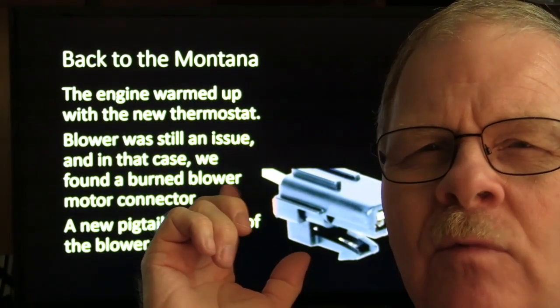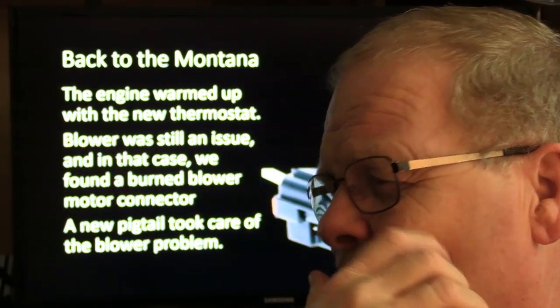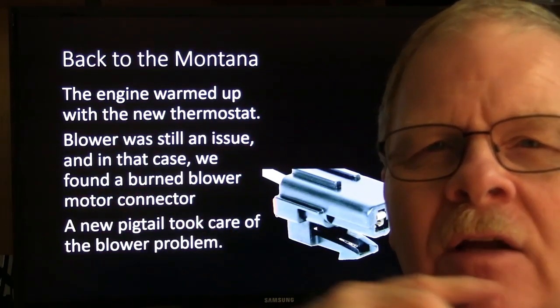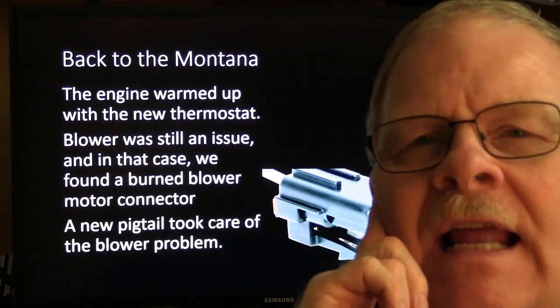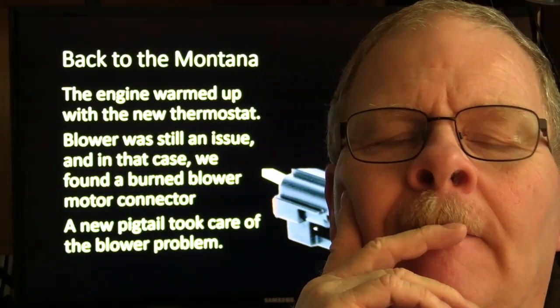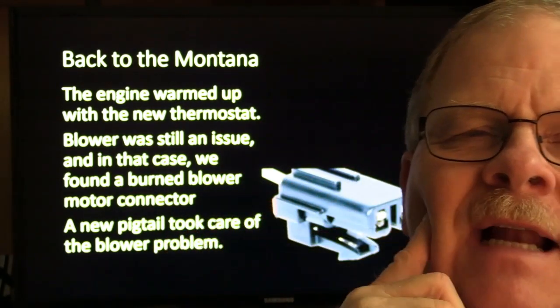And I think on this one we just scratched the surface. She said she'd be willing to take a chance by not having to buy a blower if we would just put the pigtail on it. And a lot of the times what I like to do is put some silicone dielectric grease on these terminals when I put them back together.